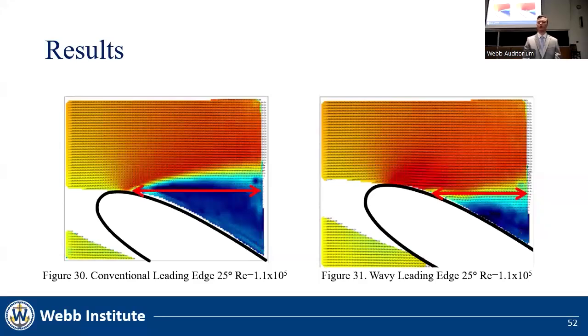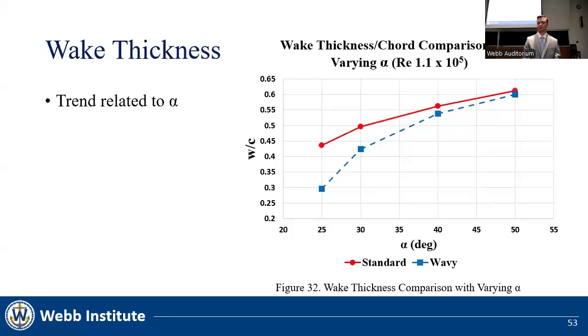The second method involved measuring the point of separation, where separation began along the chord. However, the exact position along the chord is very difficult to determine because of the angle of the camera. Instead, the 2 images were aligned in AutoCAD, and the difference in the point of separation was measured relative to the edge of the field of view. Both of these metrics are a direct indication of drag.